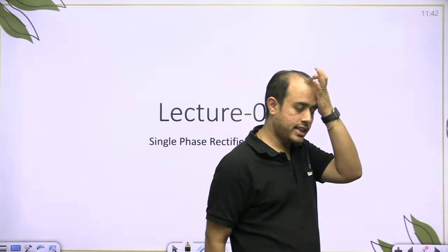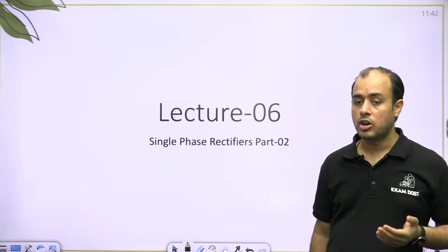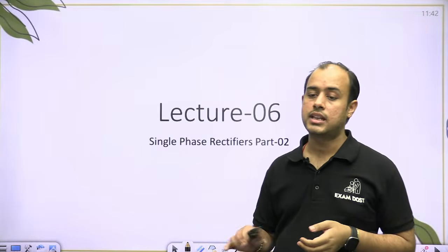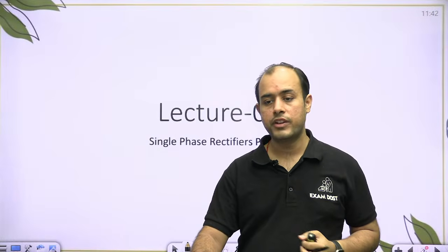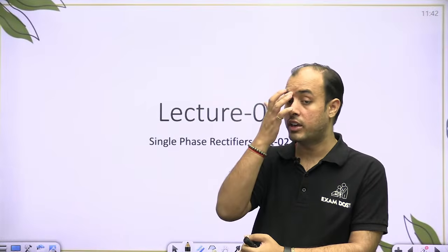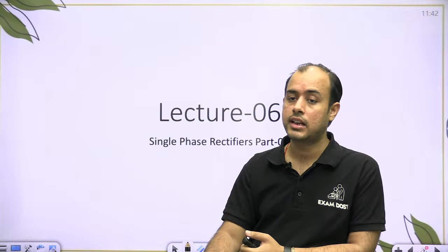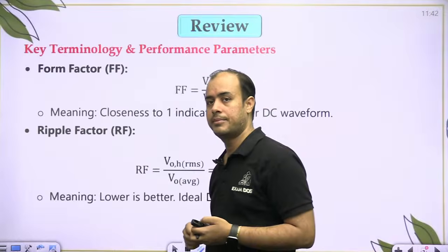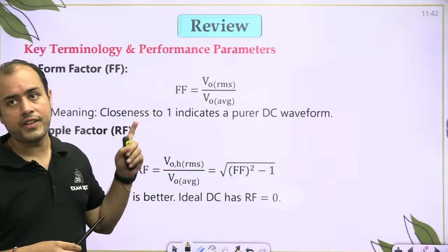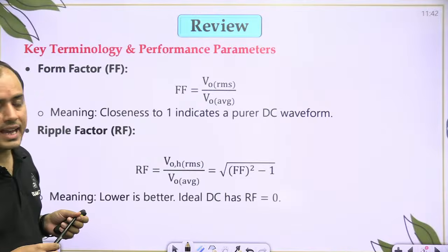Okay, so yesterday I introduced to you the concept of rectifier. I introduced the single phase half wave rectifier. So before we go any further, let us quickly recap whatever we covered yesterday. Okay, chaliye. So we covered form factor, which is RMS voltage by average voltage.